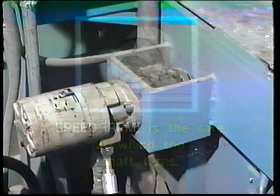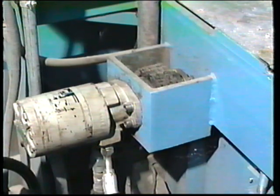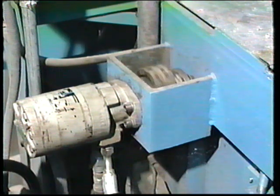Let's look at a vane motor to see how pressure and flow in a hydraulic system affect the motor's torque and speed. Like the vane pump, the vane motor has a rotating group with vanes that ride along an offset cam ring. Fluid moves in and out of the motor through port plates. As system pressure rises, the force applied to the vane increases, and the rotary force developed at the shaft, the torque, also increases. As long as the size of the motor remains the same, increasing the pressure will increase the torque. If pressure drops, torque drops.